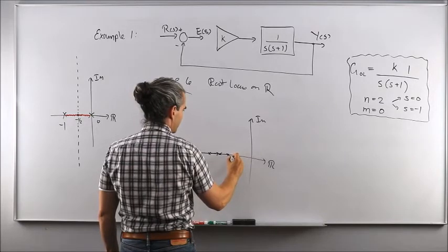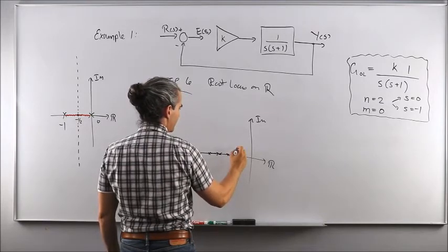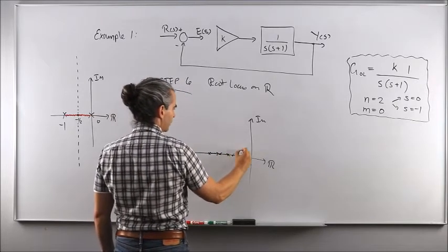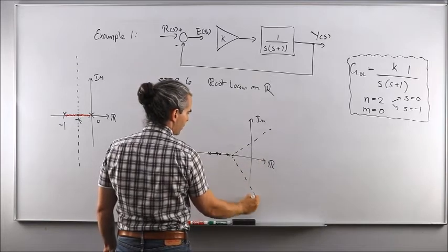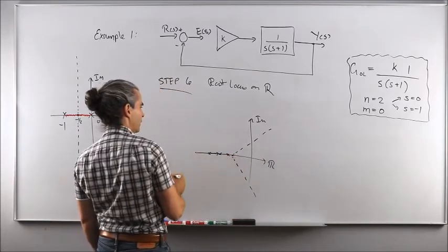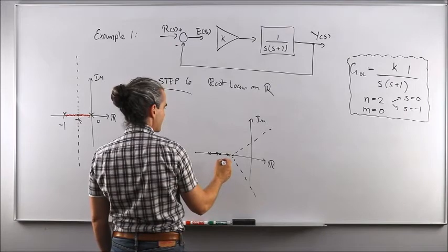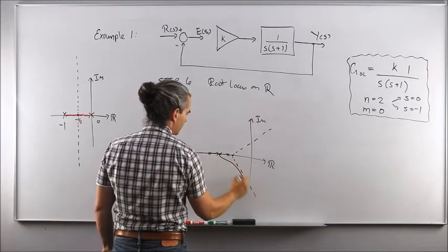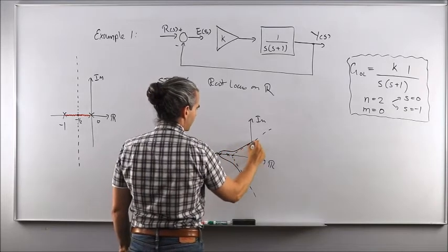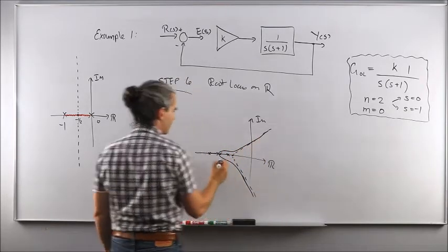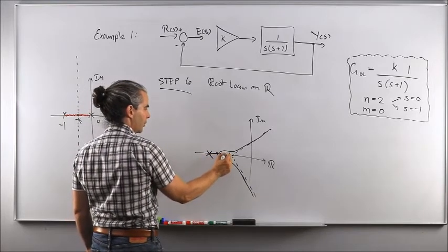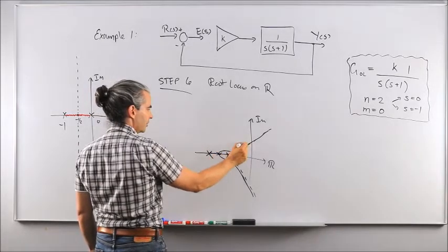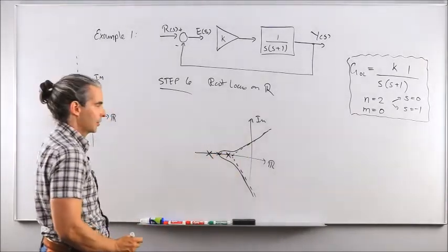So let's pretend that the intersection point of the asymptotes is here, further to the right of this pole. And that's an asymptote, another one, and obviously we need a third one. Maybe both poles would do kind of a complex maneuver like that and end up following the asymptotes, yet the breakaway point of those two poles, being in between them, would be different than the intersection of the asymptotes. That can very well happen.